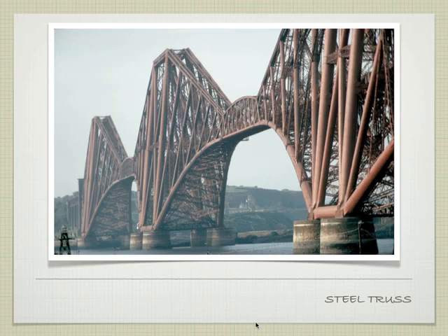All I need are the diagonals, because this is forming a triangle, which is a solid shape. I can put weight on top of this, say here, and it's going to transfer down in this particular chord to the bottom. However, if I have a really heavy point load in the middle of something like this, I may end up putting this particular piece back.